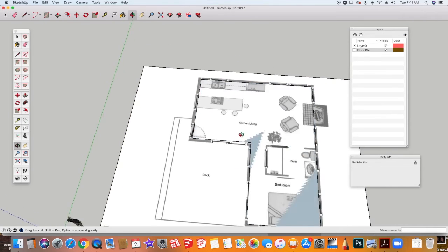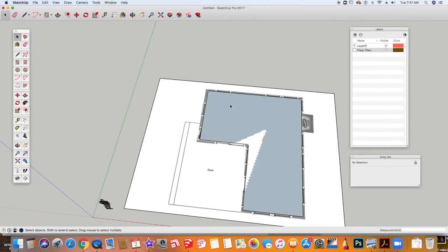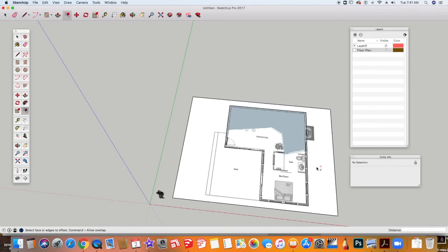Once I have my floor plan on the inside drawn in, I need to add the walls on the outside. To do this, and you might recall this from the interior design project, I need to select the floor, select the offset tool, mouse along the edge so that I get this red square, click, and start to draw out. Now I'm going to type in 6 quote for inches and click enter. And here you can see where the floor would be and where the walls would be.